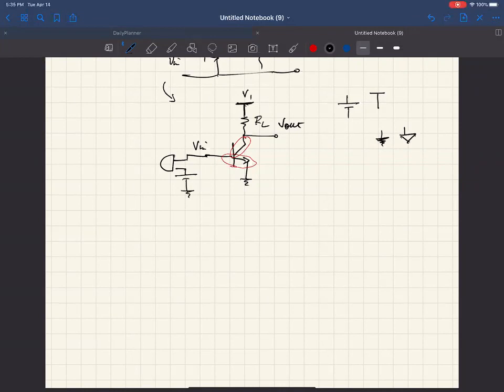So first thing is we're going to call this voltage VCC, which goes back historically, but it's the collector supply. So if you were using MOS transistors, which we'll see, the power supply will be called VDD for the drain. And so anyway, that's sort of a typical VCC. This guy, instead of R sub L, because it's hooked up to the collector, we're going to call it R sub C.